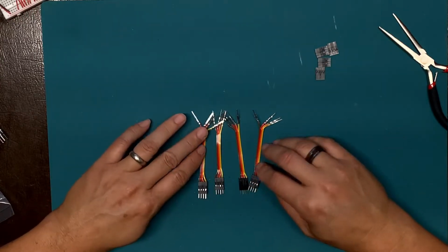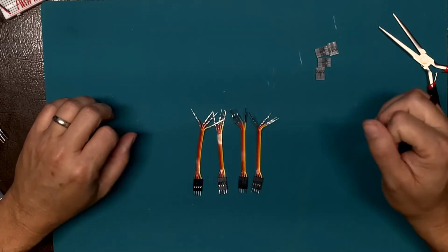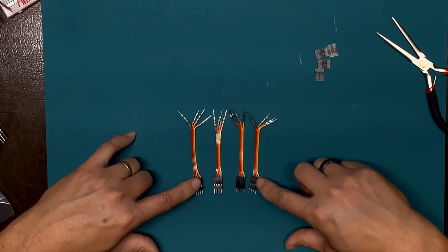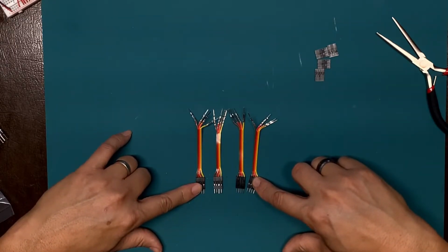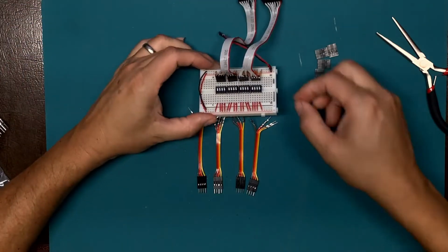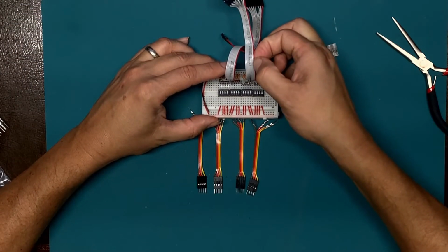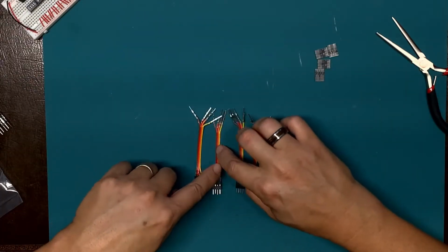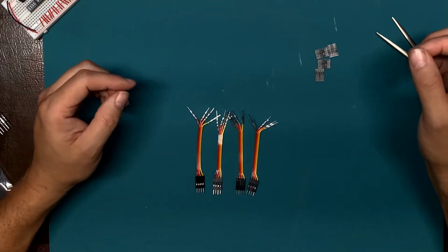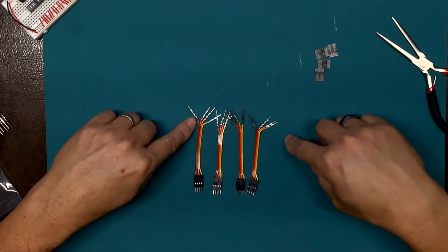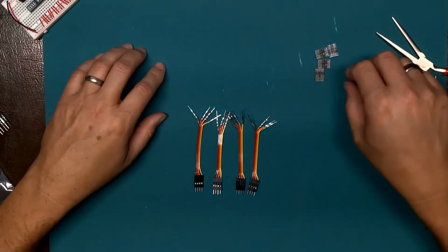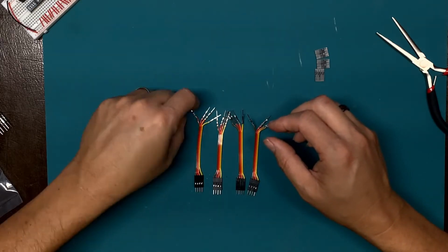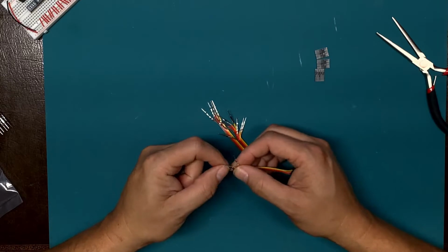I now have 4 that are prepped, and I've got one side wired up on each one. The next thing to decide is which one is going to be my low order bit. Typically on things like this, the red stripe is the low order bit, but I've got a red that's right in the middle of all of this. So I just need to figure out if I'm going to have brown be low order or yellow be low order, and it's just a matter of making sure that I get that all set correctly. I think I'm going to have brown be the low order bit.